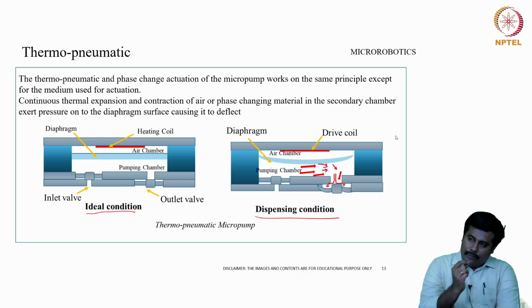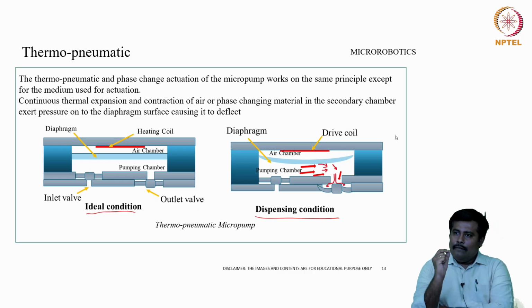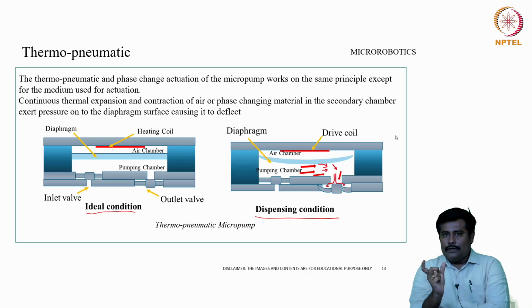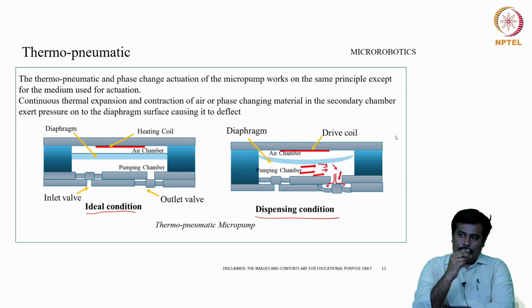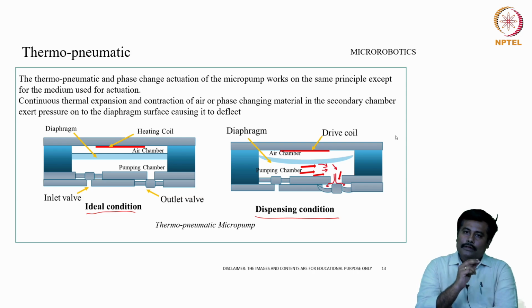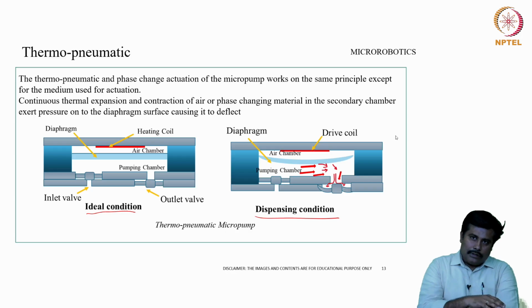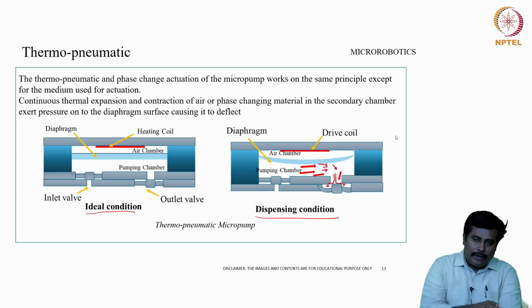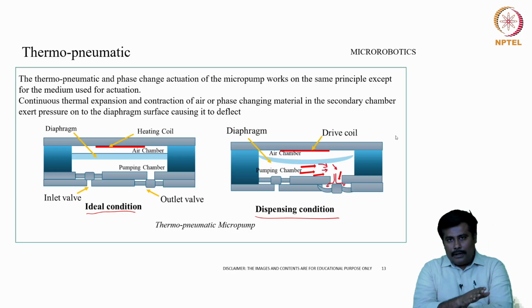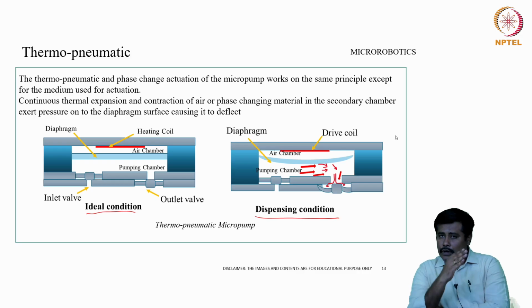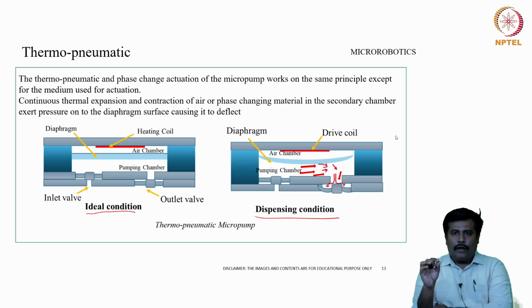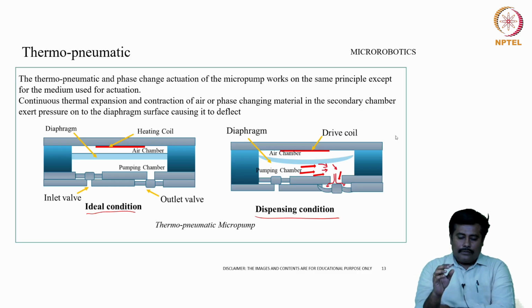In some cases we might have a thin metallic sheet where the expansion and contraction of these metallic sheets are deployed. The key parameters which affect these diaphragms basically include the thermal conductivity and the specific heat capacity of the material, which have a high influence on developing such thermal based diaphragms or thermo-pneumatic based diaphragms.